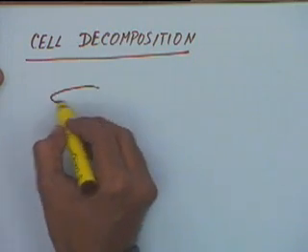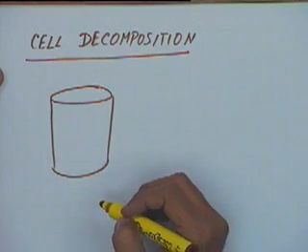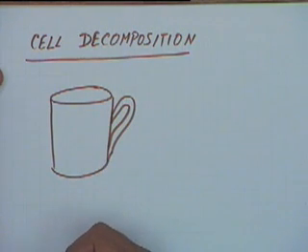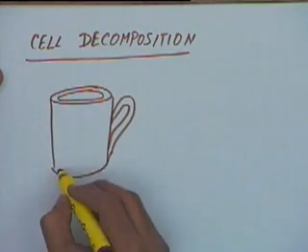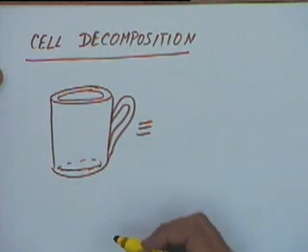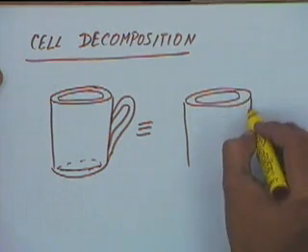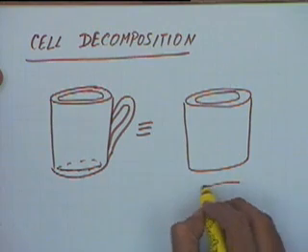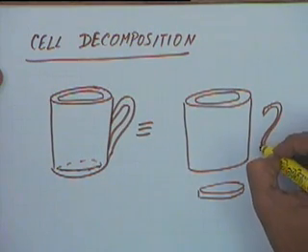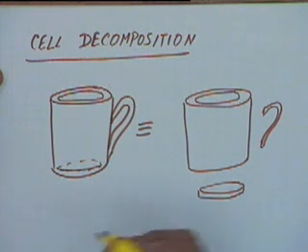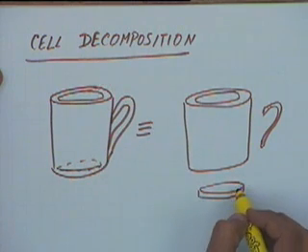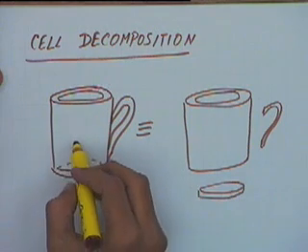So let's say if I have a cylinder like this, with maybe a handle over here. Let's take a realistic thing. It's a hollow thing, and it's got a disc at the bottom also. So this solid, I can represent by one simple hollow cylinder, its union with a disc, and its union with this handle. So what I am effectively doing is taking a solid like this and decomposing it into 3 different parts. Each of these parts can now be represented relatively easily, and I will say this solid is the union of these 3 parts.